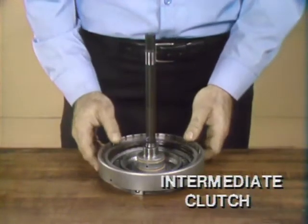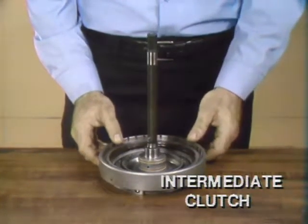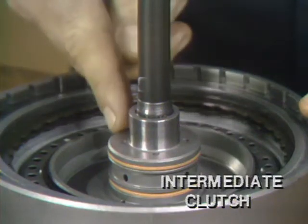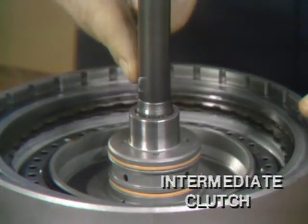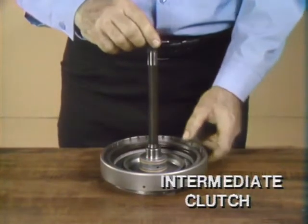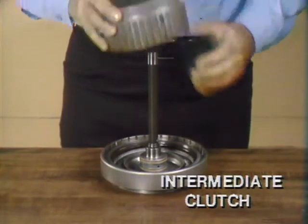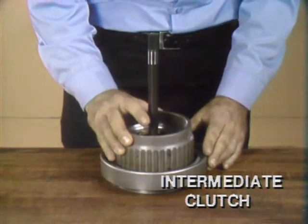There is one more rotating clutch in the ATX transaxle, the intermediate clutch. The intermediate clutch cylinder is splined onto the end of the intermediate shaft. This clutch will always be driven at the same speed as the intermediate shaft. Now watch as Joe again installs the planetary ring gear into the clutch plate splines.